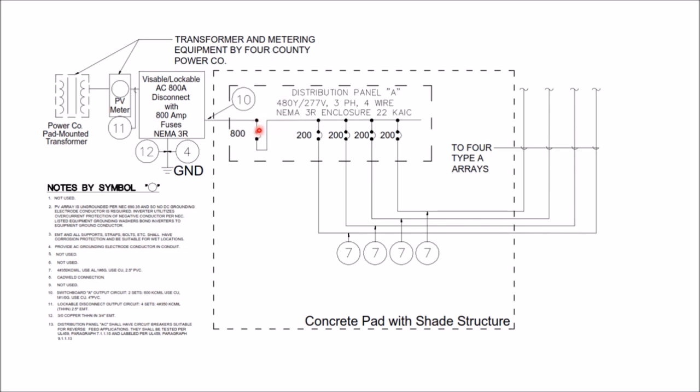By having this main disconnect switch here, we can turn the fuse off and turn this switch off. And I don't know, it doesn't gain us very much, does it? If we had tied in more than 6 of these 200 amp breakers, then we would have had to have a main on here so that you could turn off one breaker and kill power to the utility.